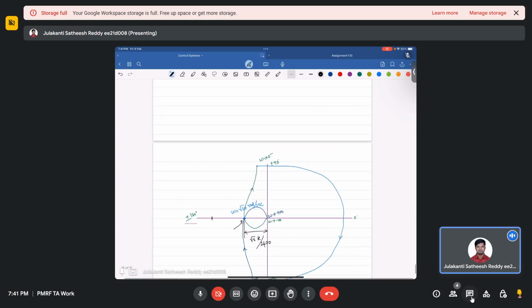So when we have the transfer function G of j omega H of j omega, we say that the transfer function is equal to G of s by 1 plus k G of s H of s. Suppose this is k. Now we are only interested in the denominator part. This is the characteristic equation, del of s equals 0. For certain values of k, the transfer function poles will be on the left half of the s plane, so that the system is stable. We say that.